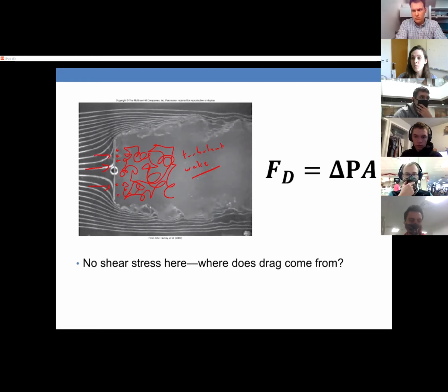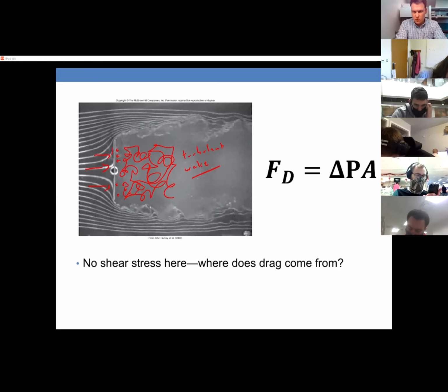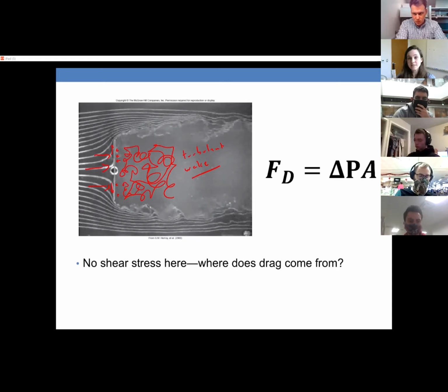Dr. Nickerson? Will the fluid not produce any friction on the plate? It will a little bit, but in this case, the friction drag is going to be really small, because the friction comes when it's rubbing alongside it. Here it does a little bit, but that drag will be small compared to the drag that comes from the pressure. Someone said my name. I wasn't sure who it was.